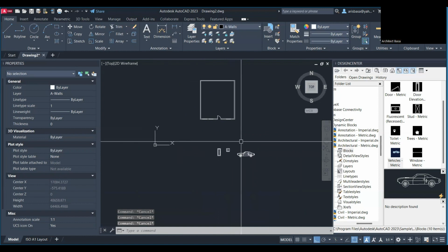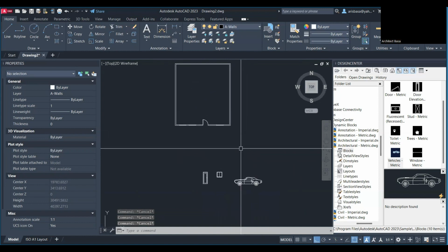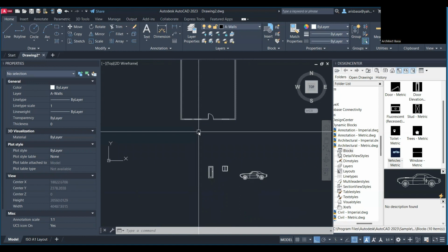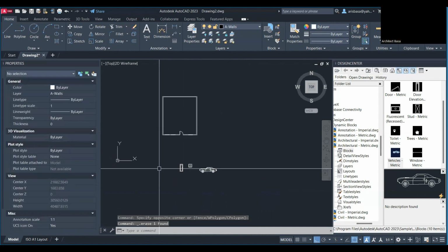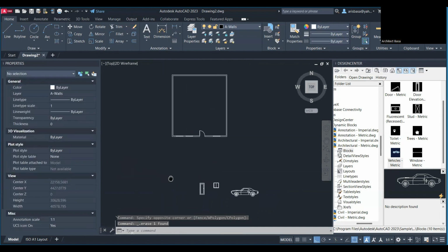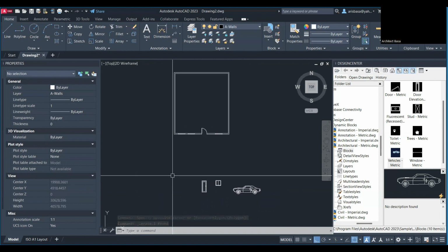So usually the way to do the front elevation is to project the lines of your plan. Okay. So to do that, you can draw a line like this and just draw it straight like this. But there is a better way. Okay. I'll delete that. We have a tool or a command called X line.